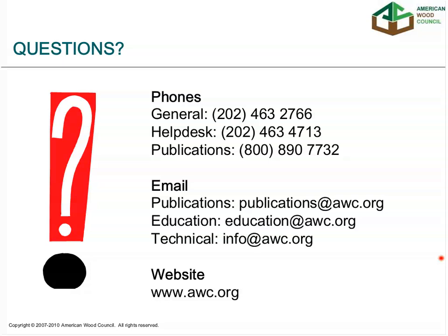Next question, does C sub M have to do with cross-grain tension more than the hole size changing when the moisture content under fabrication is greater than in service? And it's probably a combination of both there. For the moisture adjustment C sub M factor, it is going to deal with cross-grain tension. It is going to deal with hole sizes changing in service versus as fabricated.